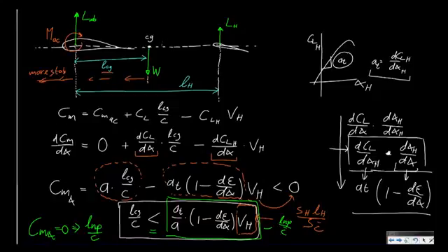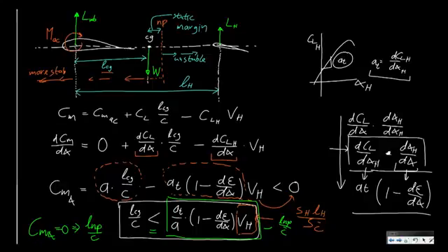And there is a position here, the neutral point, on which you're on the verge of instability, and if you go in the other direction, you will be unstable with your center of gravity if you move it here. And therefore the distance between your actual center of gravity and the neutral point is your margin, and this is called your static margin. And it shows the margin you still have in the aircraft.